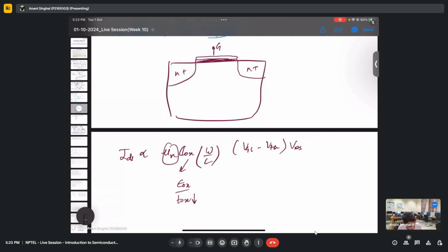So there will be electrons going to and fro from the gate to the channel, so gate leakage can happen. So we do not prefer to decrease the oxide thickness. What we do instead is use materials which have a high K permittivity, or high K materials as we call them, to have more and more current.